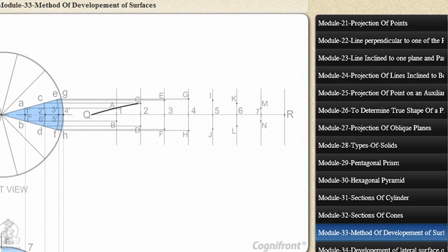Draw smooth curve through points Q, A, C, E, G, I, K, M and R. Similarly, draw smooth curve through points Q, B, D, F, H, J, L, N and R. Thus, the figure obtained will be the approximate development of 12th portion of the surface of the sphere.